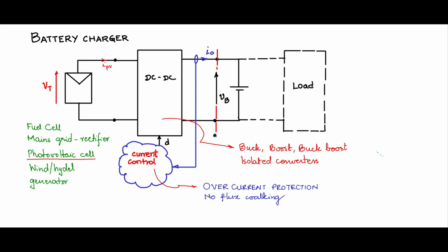So now let us see how this battery charger is built. Let us try to understand the principle of operation, and then let me go into the circuit and give you the schematic for controlling the DC-DC converter for current control. And later I will be explaining some problems that we will also address by providing slope compensation.